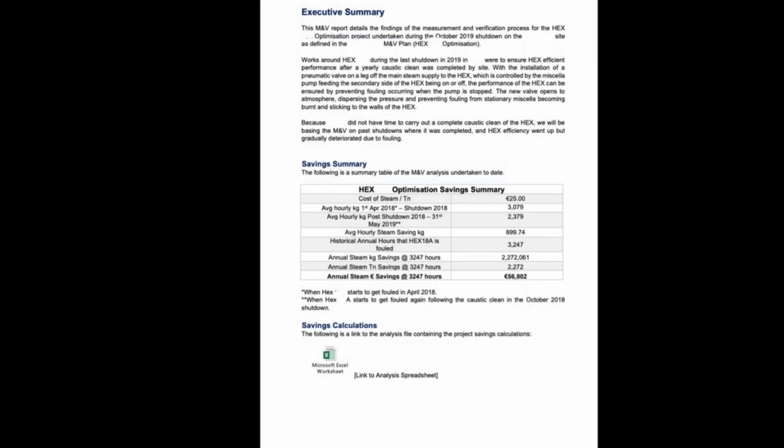By modeling the process around this hex and trending how it should be operating, it was found that there were further savings to be achieved as it was still consuming too much steam. The hex was increasingly becoming fouled between shutdowns where it will ordinarily be chemically cleaned. With the insight of CoolPlanet OS, we were able to pinpoint when and how the hex was fouling. On average, these circumstances only occurred 5 times a year, but had huge impacts on steam consumption.